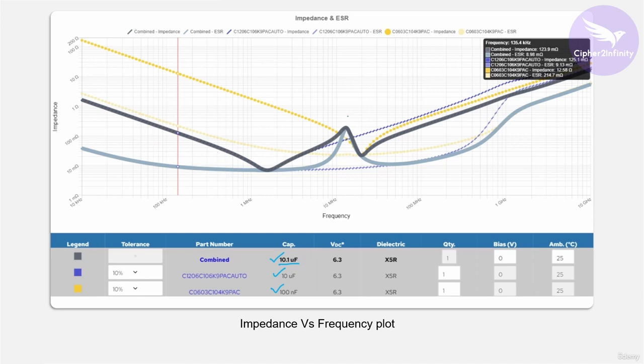Here you are actually getting a peak. And for this particular peak, the impedance is 200 milliohms. So it's completely fine. Even if there is a peak, no problem. 200 milliohm impedance is also very low. So a good range of frequencies you are actually able to filter out when you connect multiple capacitors in parallel. So remember this particular point.